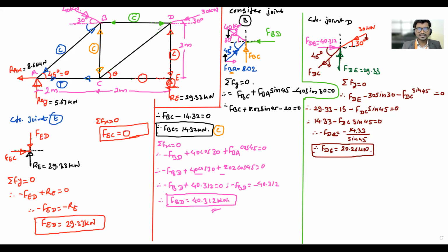At joint D it is down, at joint C it will be up. So is the member compressive or tensile? Tensile. The member is in tension, so I would like to write here T. Now if you go for the summation of Fx, you will get the answer 0. Do you want to check? Because now we know the force in member DC, we know DB, and we know this 30. In the summation, these three will come and their sum will be equal to 0, something like 0.000.